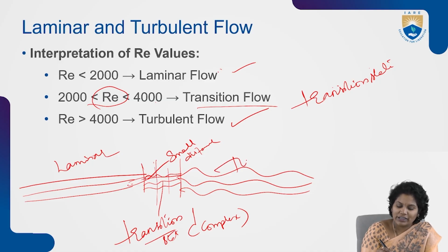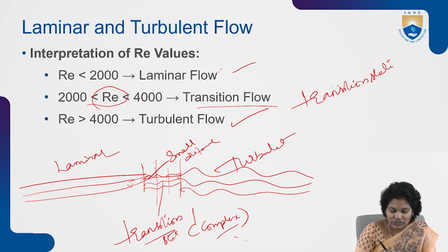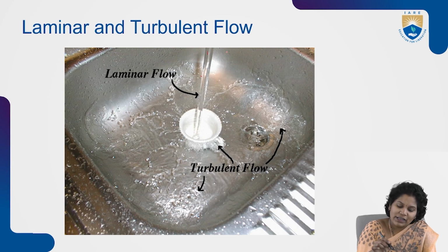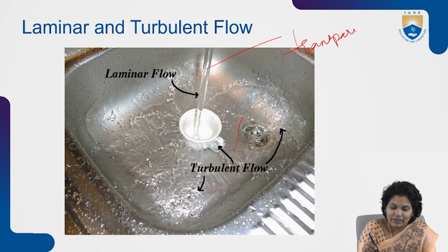So this is laminar and here is a turbulent nature. It is very complex to find out the transition state, right? See, this is a laminar flow and here is a turbulent flow. There we are seeing some disturbances in the flow, and in the laminar part all the particles are moving in very well-defined paths. Due to these well-defined paths, the flow is very transparent, right?